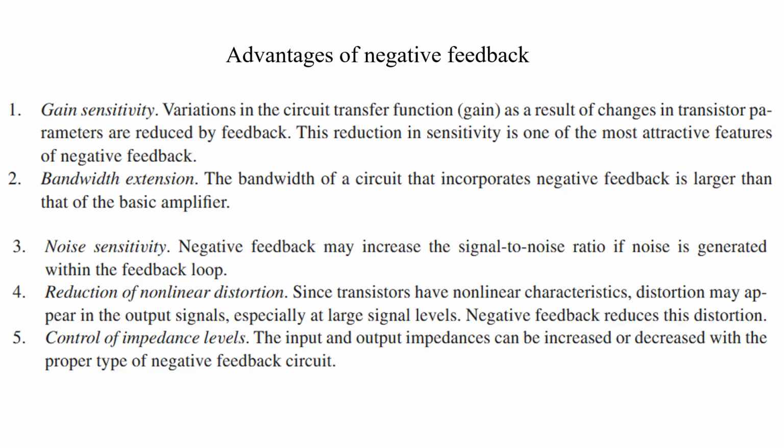So what are the advantages of negative feedback? First, gain sensitivity: the variations in the circuit transfer function, that is the gain, as a result of changes in the transistor parameters are reduced. Also it will be independent of temperature, which is another advantage. Bandwidth: the bandwidth will also be enhanced with negative feedback. Noise sensitivity: negative feedback may increase the SNR if noise is generated within the feedback loop.